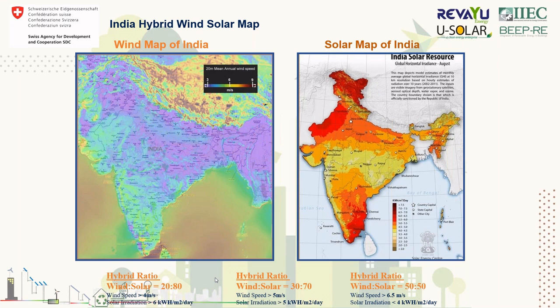And even though wind could be expensive than solar, wherever we have wind speeds more than 6.5 meter per second, whether it is India or globally, it makes very good sense to even have a mix of 50-50 over there, because wind would be producing much beyond what solar can produce in that mix, and will be justifying its commercial difference.